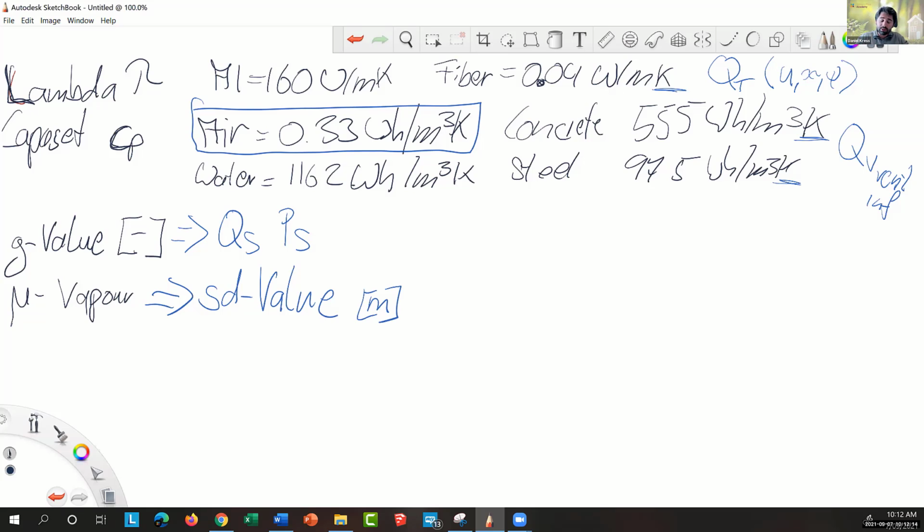So Passive House is optimizing now the building envelope. And now we sometimes even get away with using direct electricity in a bathroom, where we're switching it on for 10 minutes, 15 minutes, like a little fan heater would be okay in that case, because the demand, the amount of energy that we need, is so small. So in a Passive House, if the conditioning system is not so efficient, it's not so important, if it's for short periods, like a bathroom heating or something like that.